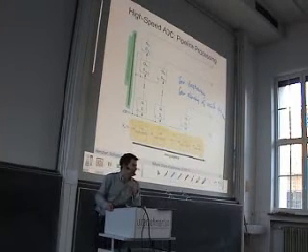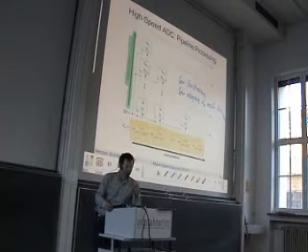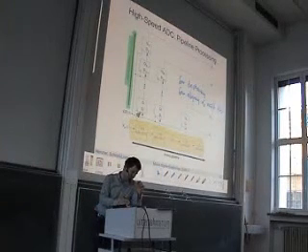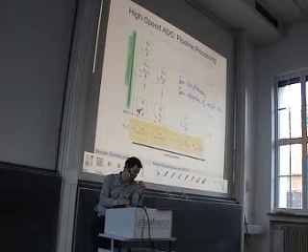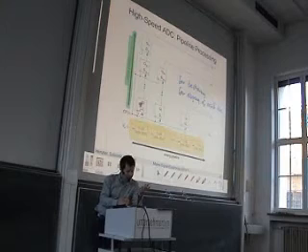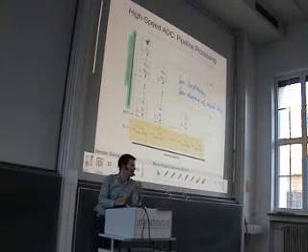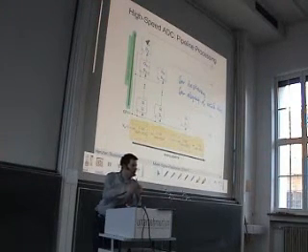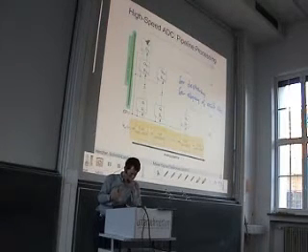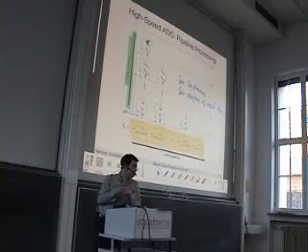A common failure that is done here is to say, okay, in the first stage I have to delay the result n times. So I do not take n flip-flops in series, but I take a single flip-flop and I subdivide the clock by a factor of n. This would reduce the effort considerably.